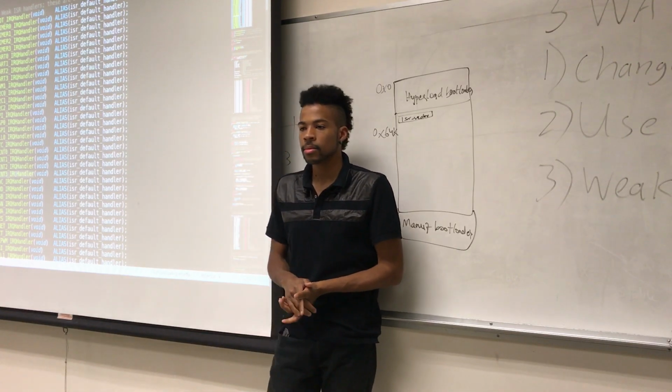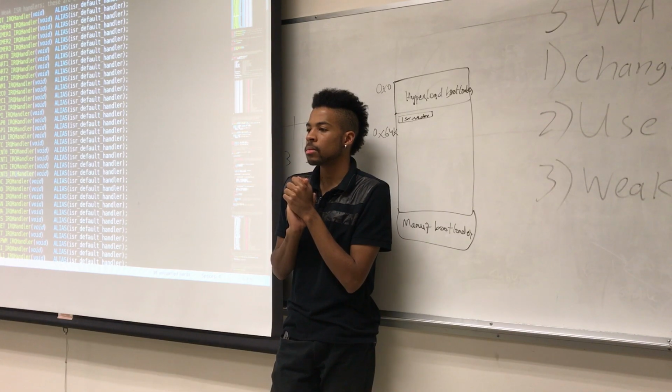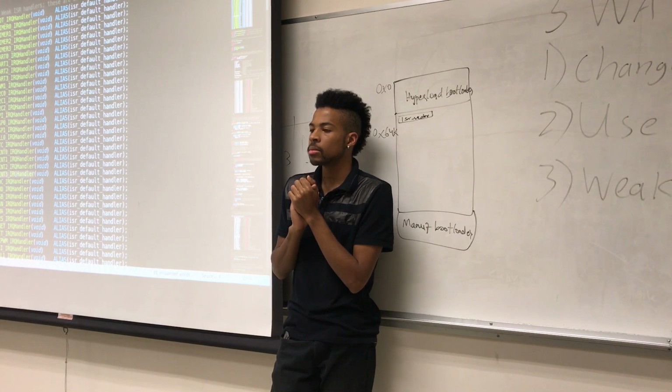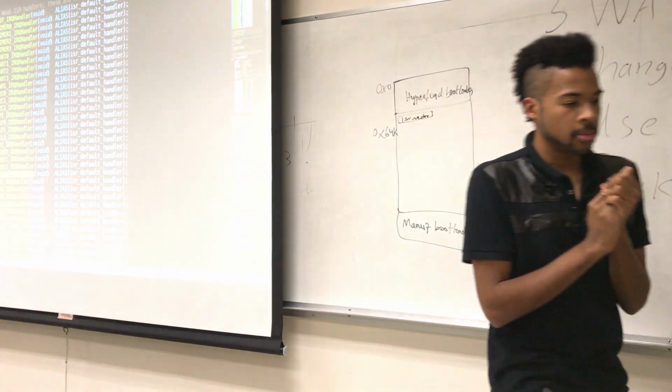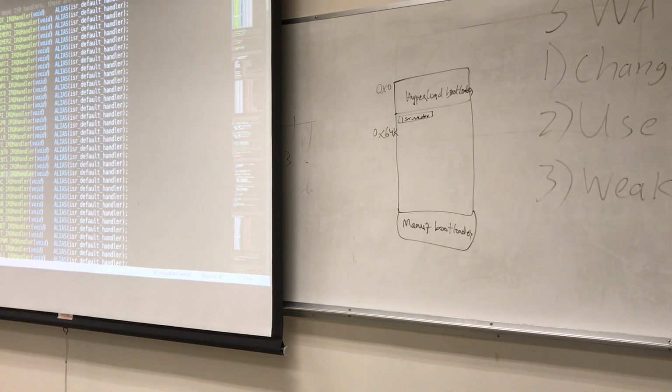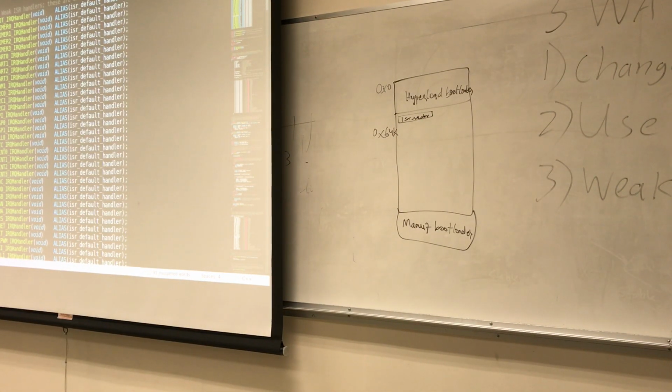So when I read through, I found that external interrupt 3 is only identified on one of the pins for port 2. One of the pins. Do you know how you determine what the function is on a certain GPIO pin? Mm-hmm. I only found external interrupt 3 on one of those pins in port 2.